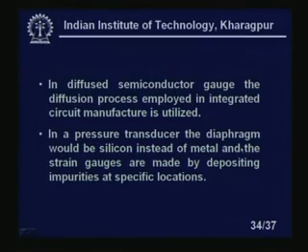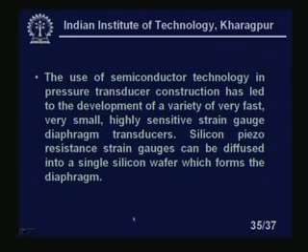So, I am not using any metals, I am not using brass, steel, anything. I am using the semiconductor wafer itself as a diaphragm, and where I want the particular strain gauge, that position will be doped, right. The use of semiconductor technology in pressure transducer construction has led to the development of a variety of very fast, very small, highly sensitive strain gauge diaphragm transducers.